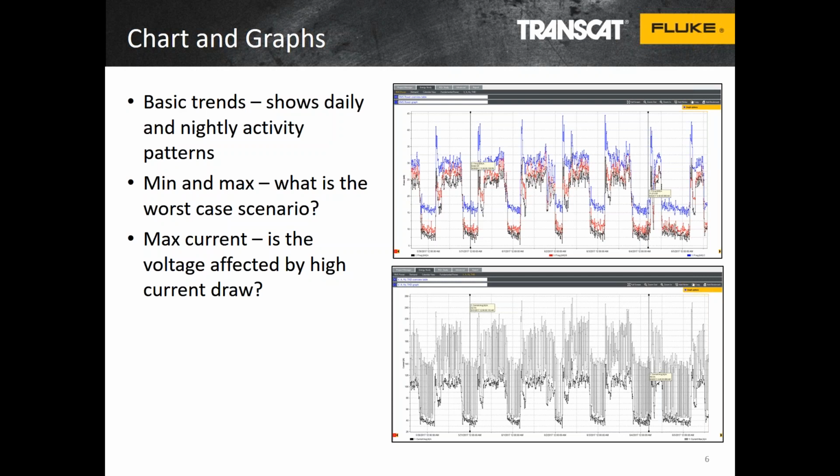And once you understand what those loads are, it becomes a lot easier to understand why the pattern of the energy consumption or power quality problem is what it is. So you have to become somewhat of an investigator. You have to know the right questions to ask. Most of them are very simple questions, but it starts to enable you to create the story behind the graphs. And then when you show the people who have asked you about what their energy consumption looks like the graphs, they get it. It's really straightforward. You can identify which loads come on at which time.